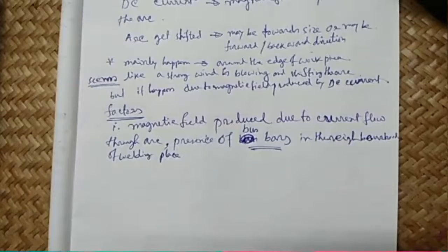So at the bottom, where penetration is required in the groove, the arc does not reach, the arc connects to the burrs. As a result, you do not get the penetration you required. The arc does not melt the material in the groove, but produces heat beside the groove on the edges.